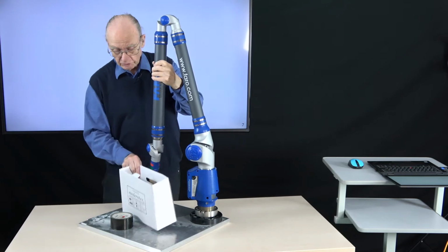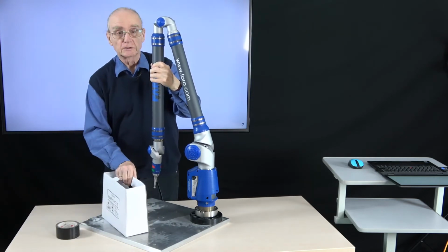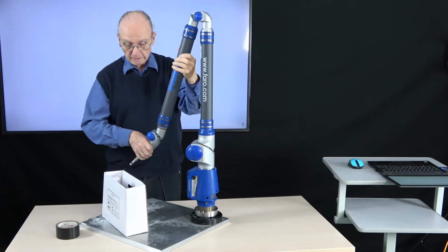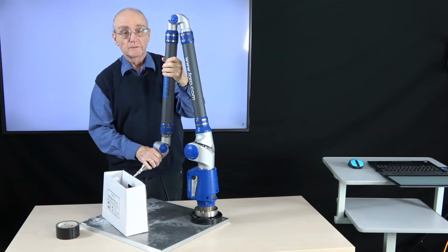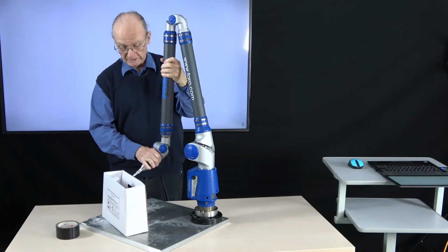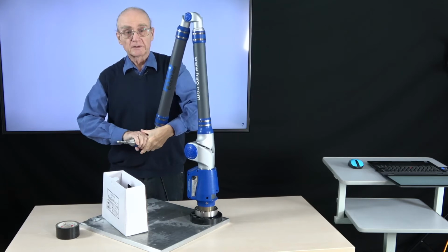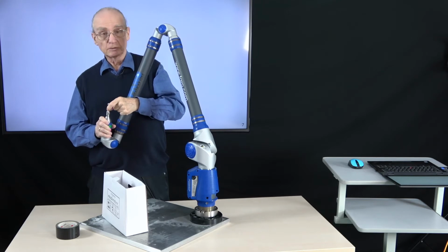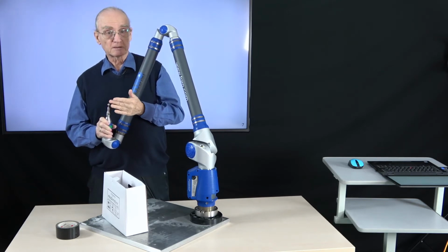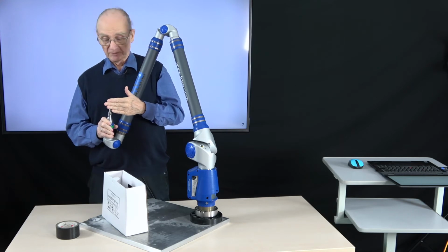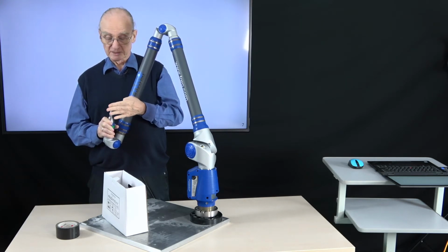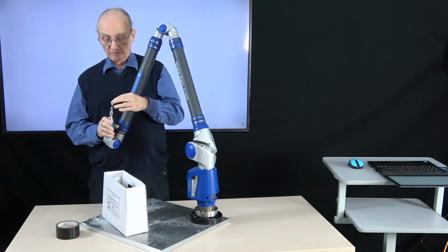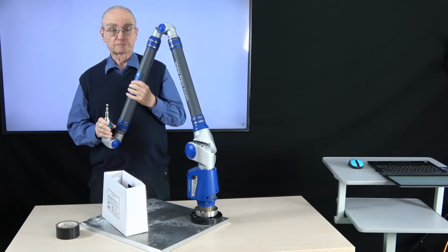Or you have such an object where you want to measure the thickness of this part, and then you can actually go on the other side and measure the surface point from the other side. The technique is such that this measuring ball has a sensor which identifies that it touches a surface and then knows from which side, and then because it's a ball, it knows how to transfer the position of the ball to the surface point.